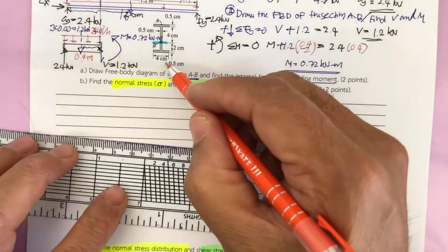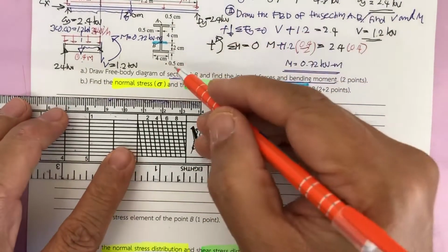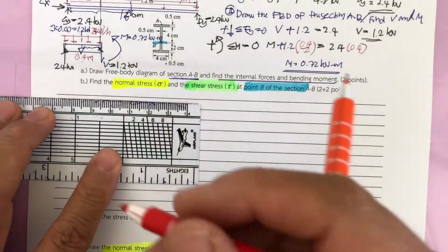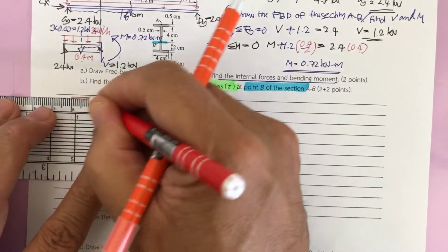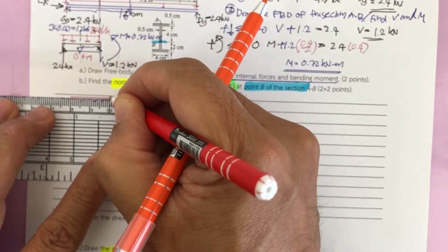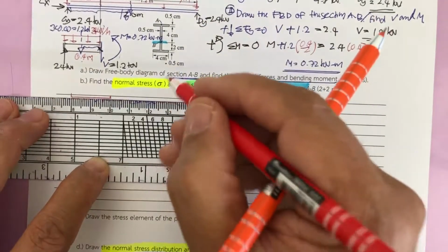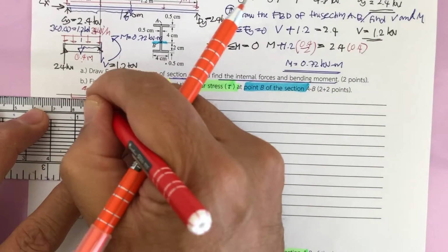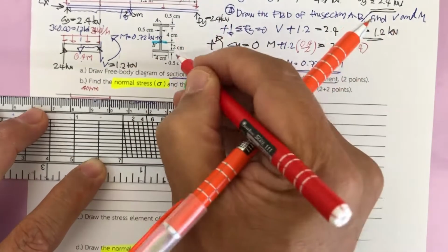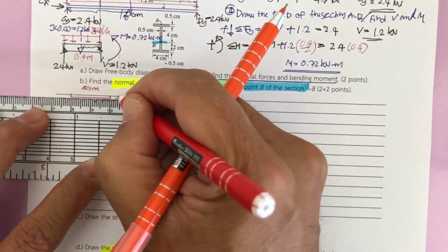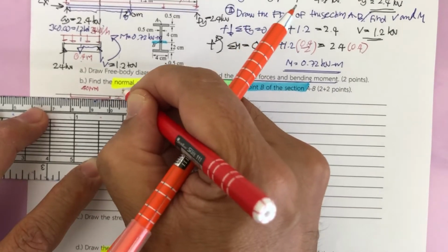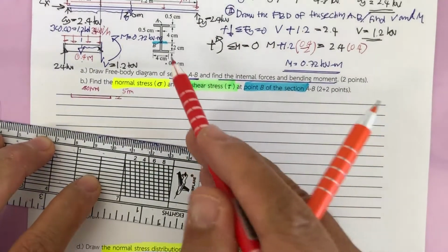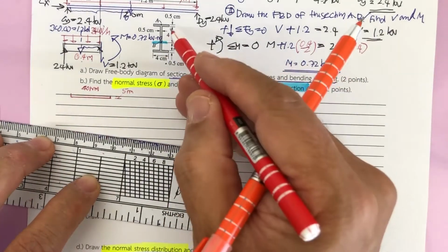This is 4 centimeter or 40 millimeter. Let me put this one in scale. Let's put this one for 2 centimeter, that is going to be half of this. This is 4, this is 2. This is going to be 40 millimeter, and the thickness of this is 5 millimeter. That is going to be the top portion of this section, or this is the top flange.